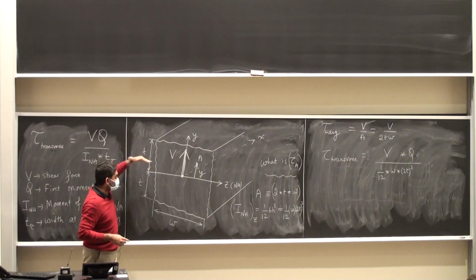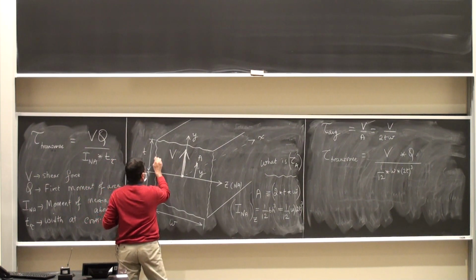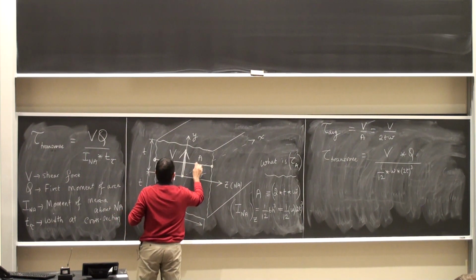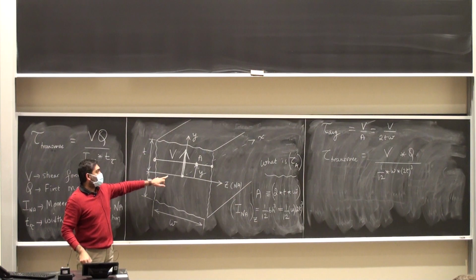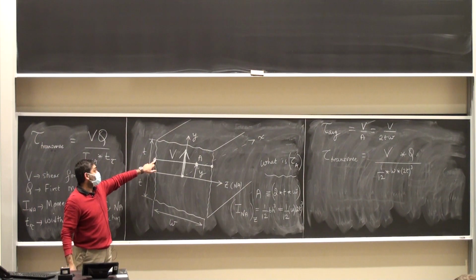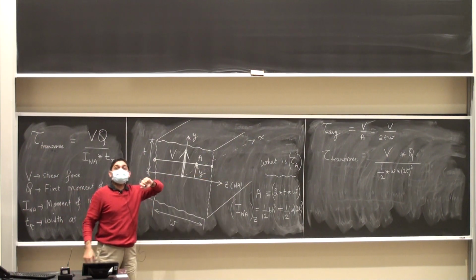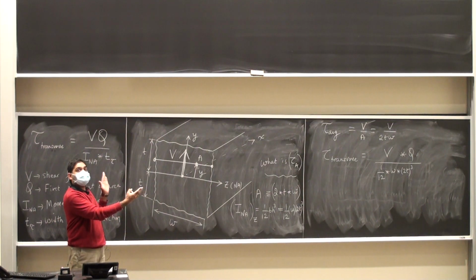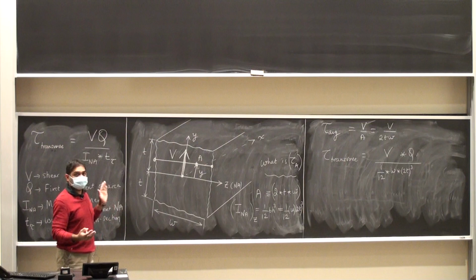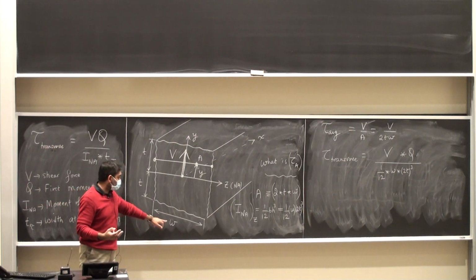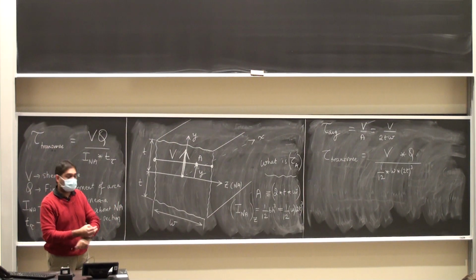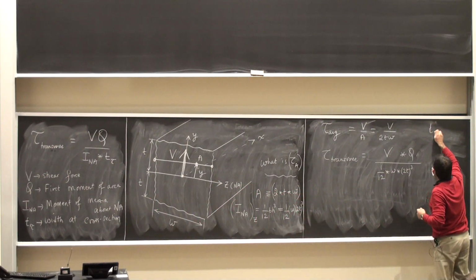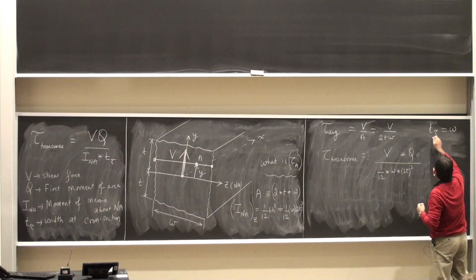That line will intersect this point. So here is that line. This line is parallel to the neutral axis. It starts from one end of the cross section, goes all the way to the other end, and the total length of this line is going to be t suffix tau. And in our case, that is nothing but the width of the cross section. So t suffix tau is W for us.